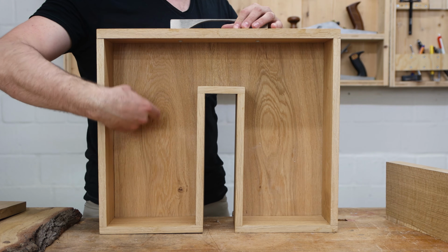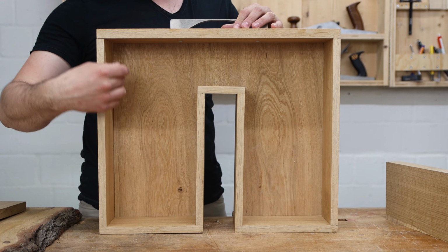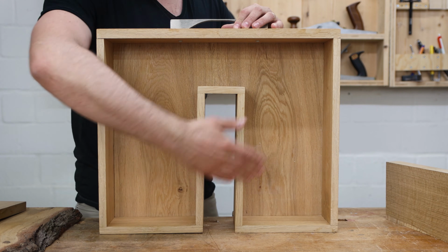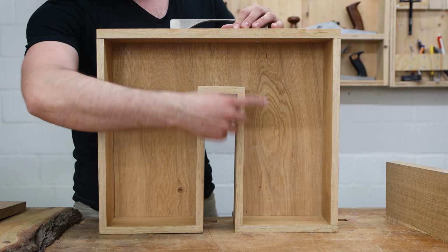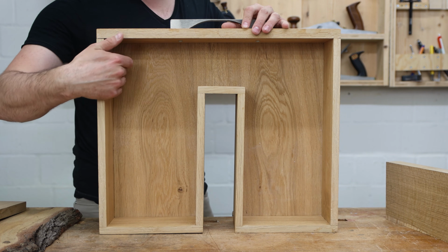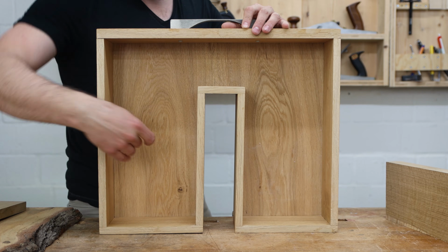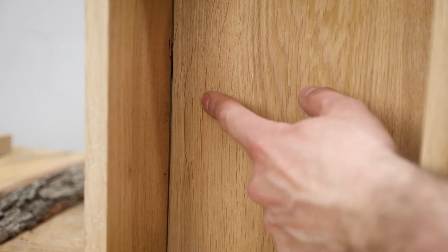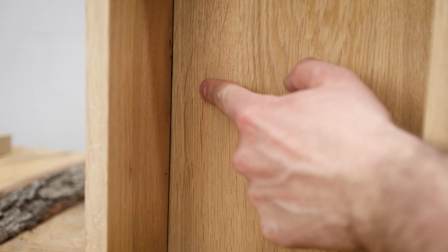The drawer bottom is actually pretty similar to a frame and panel construction. The frame is not going to change much in its dimension. As you can see in my example here, the drawer bottom contracted a little bit here and I did not leave enough room to allow for the wood movement.